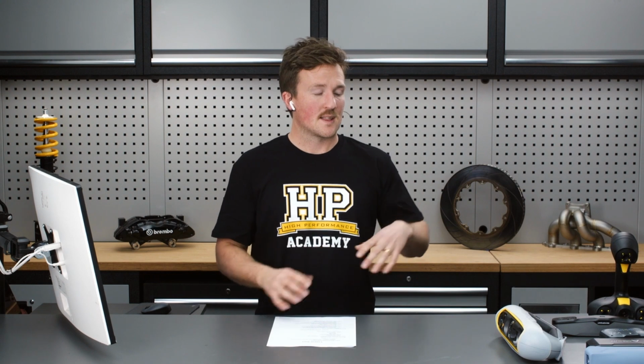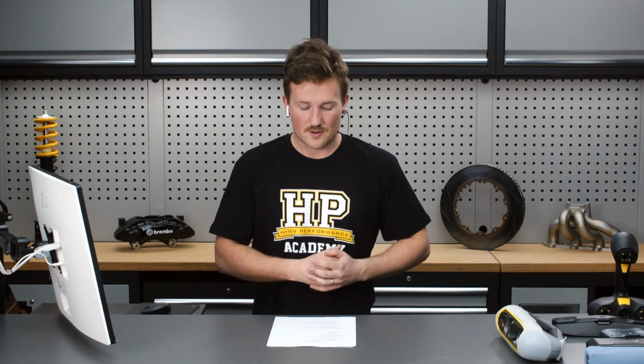So if we combine the benefits of a laser scanner being able to deal with those surfaces, and also a structured light scanner for just the efficiency of capturing data, then we can get the best of both worlds in that case. So I'll just make a note here.